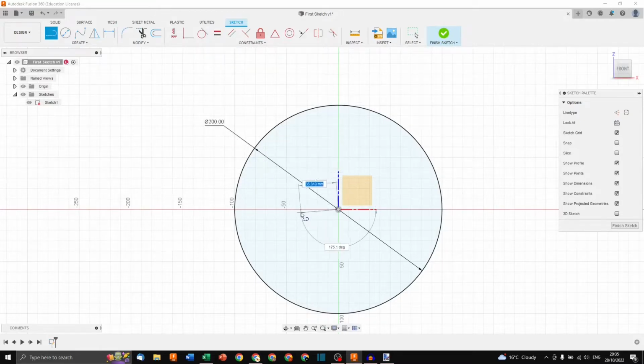It's saying that it's making a horizontal constraint, and you can see it snaps to the red line, which is the horizon. Once again, you see, it snaps to the circle and gives me an X. X means coincide. So I just added a line with 2 constraints, actually 3. Coincide with the center of the circle, coincide with the outer diameter, and be horizontal. I could also not snap anything and put a random line here, let's say.